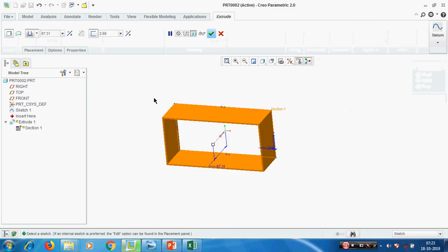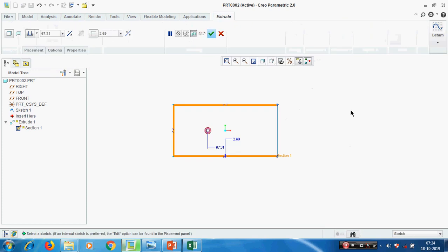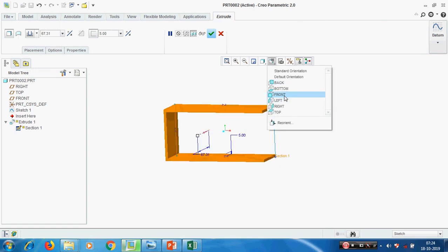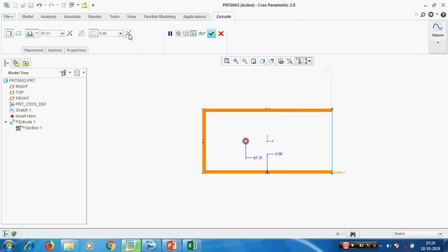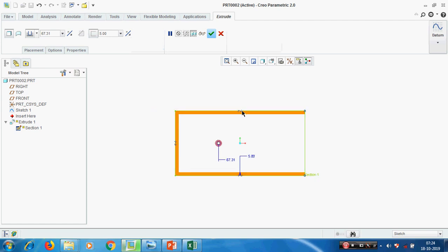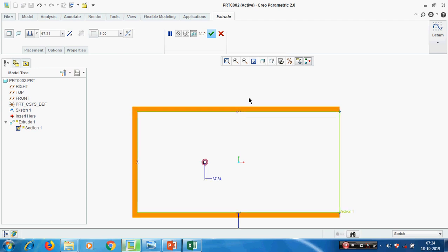Now we will try with the open edge, placement, edit, sketch. Now I am removing one side, this one. So for an open loop also we are getting the thicken feature, 5 mm wall thickness, 50 front. See, by flipping this, we can change the thickness direction. Now the topmost is the sketch. The sketch line we can see. If you pick, now see, it moved to top.